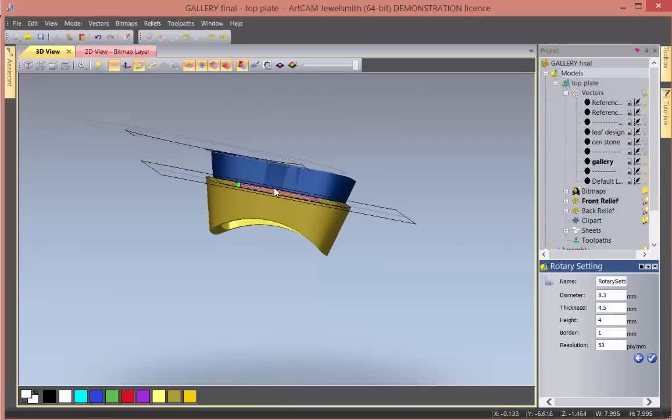Okay, how thick is the model? So we know the model, let's just add in 10, which will give us more than enough space to work in. Since the model is only about 5, we're just going to add in 10. So when it opens up, there's going to be plenty of space on either side. The border we can leave on 1.